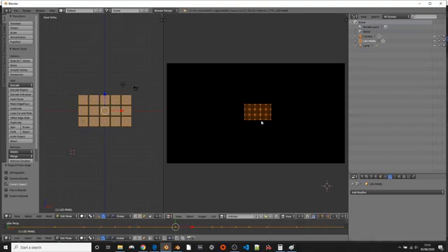I'm going to have a look at things like maybe making models for morphing. I could probably do that on the 3D models one, actually. And I'm also going to have a look at using products like MyStrip. So MyStrip is a particular brand. It's a video product, and generally it shows 128 pixels by 1 pixel. You get a lot of variations on this theme now. But quite commonly you'll see people using them in a circular configuration on, say, the floor of a game show, a television show. But in reality you want a load of straight lines on your output because no LED processor will happily work with circles. It likes ups and downs.